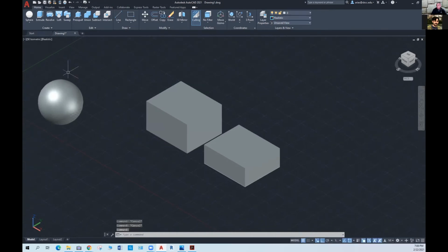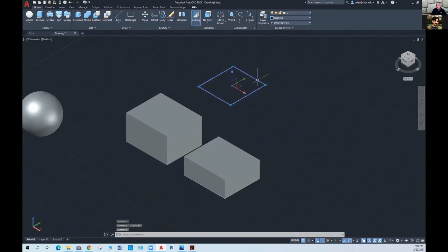So once again, remember, we can create solid geometry with the primitives, or we can use these profiles, right? If the profile is made up of lines or line segments that are joined as a polyline, then the resultant 3D object is going to be a solid.